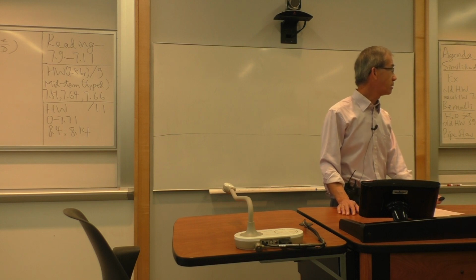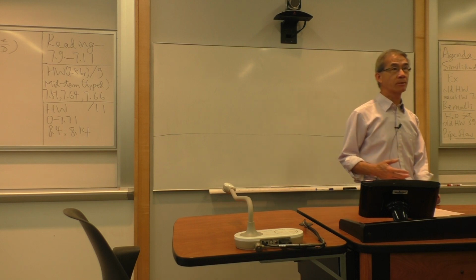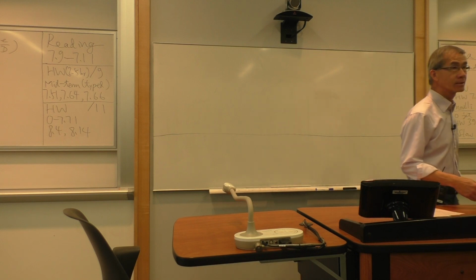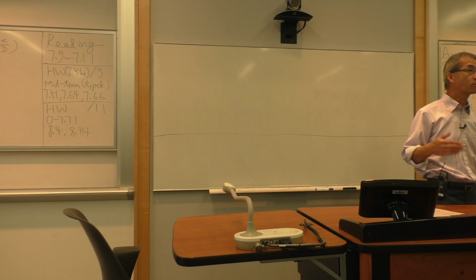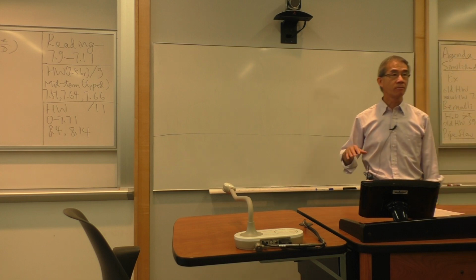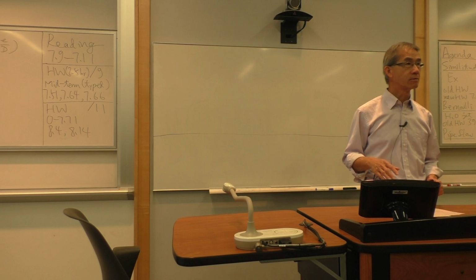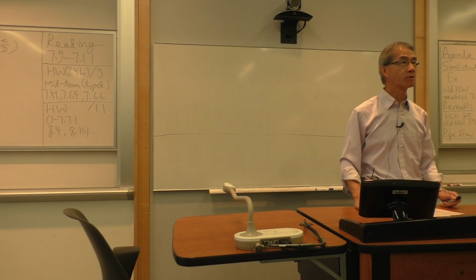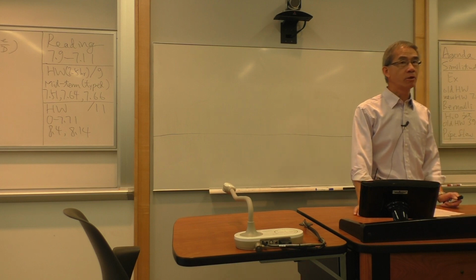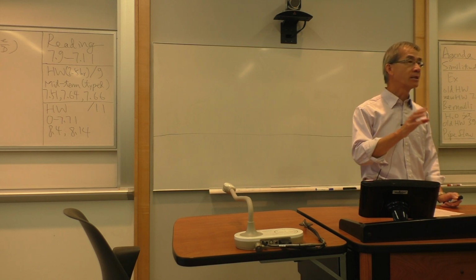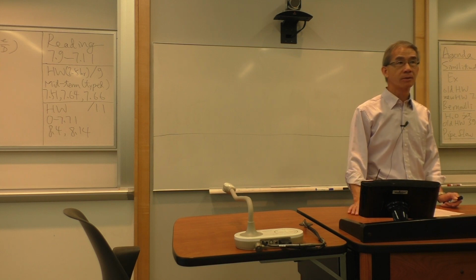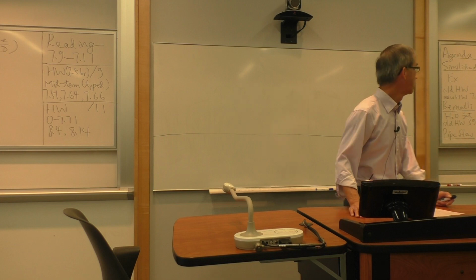So that's what we started as a motivation for this chapter of dimensional analysis. So we went through all the pi terms. Now the rubber meets the road. And that is, how can I take further advantage of that to do a cheap, inexpensive experiment and make sure the data from my wind tunnel can be used to extrapolate to an actual full-size Boeing 787 Dreamliner.